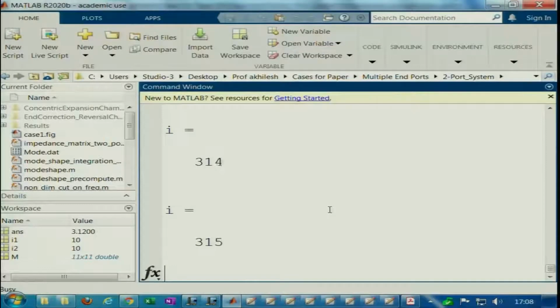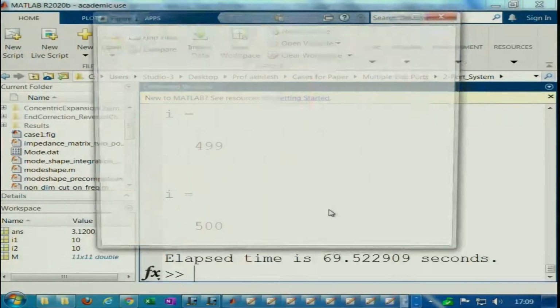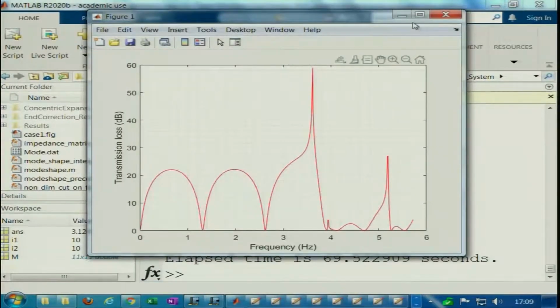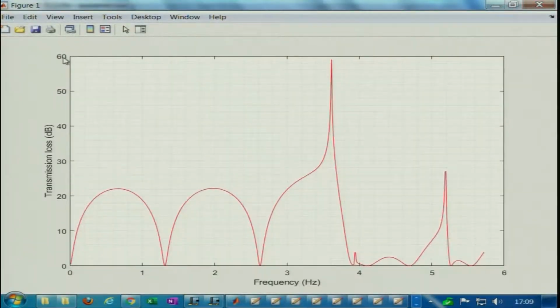It is about 500 time steps, or frequency steps, that it has to do, so we will be there in just a while. We will still see this expansion chamber kind of behavior, domes and troughs, but the sharp, peaky attenuation peaks will happen at a much later frequency, possibly from k naught r naught equal to 3.05 onwards. So you can offset one of the ports, and basically compare this with the graph here.